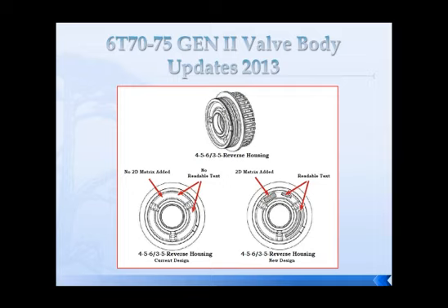Clutch drums also changed. As you can see here, we've got a picture of the 4.5, 6, 3.5 reverse clutch housing from the back. And we're saying part of the ID could be simply looking for the part numbers that are embedded into the back of that support.